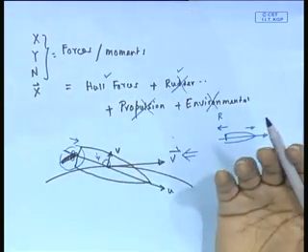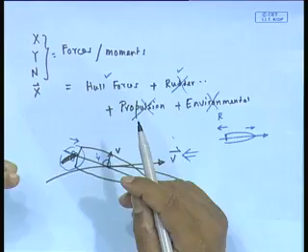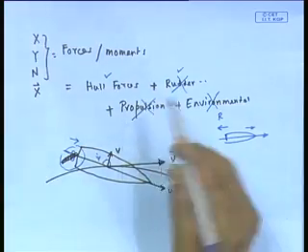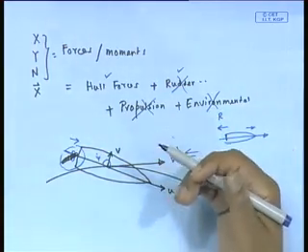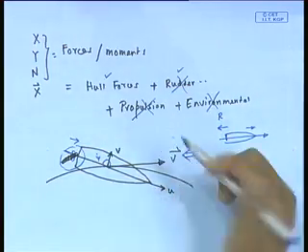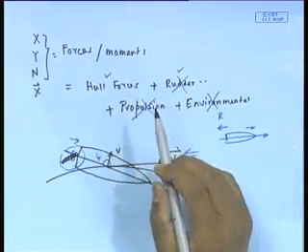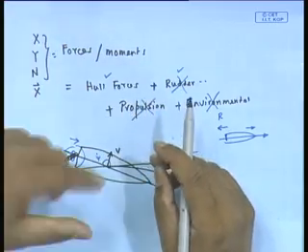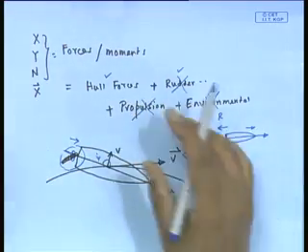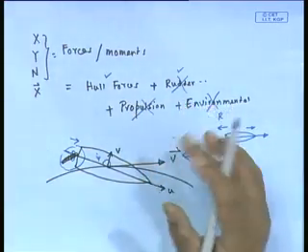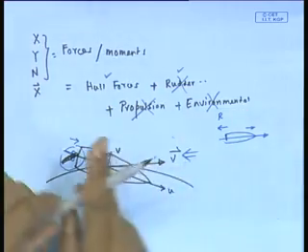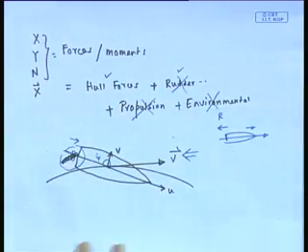It was not there. Rudder force I am actually imposing, I am basically giving a rudder angle so that there is a force coming. Propulsion I am having an engine operating. Environment I do not have a choice, it was there, waves, current, etc. It is the hull forces that got created because I am turning or I am having a non-zero V, R, etc. Means it is not going along a straight line. That is what I want to look at first.